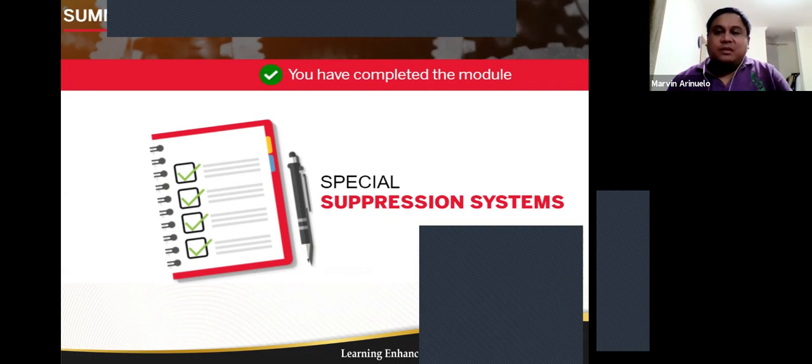So you have completed this module. Just to recap, because there is also part A of this, you became familiar with water-based fire suppression and fire suppression without the use of water. We discussed the properties, extinguishing characteristics, and limitations of your extinguishing agent.